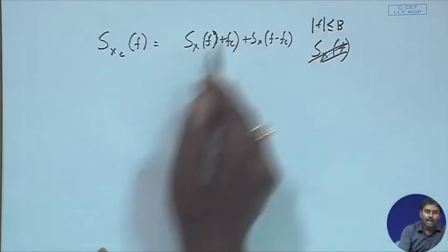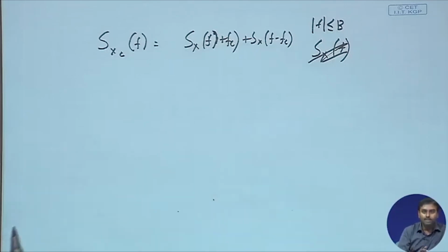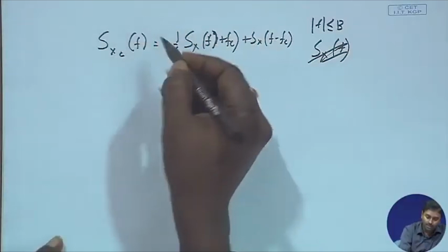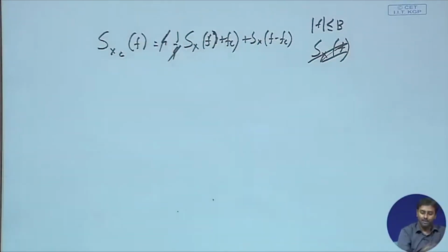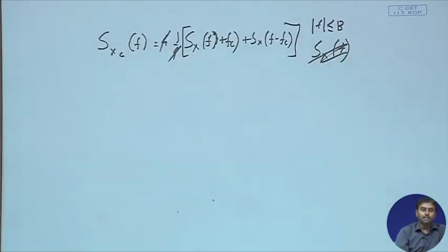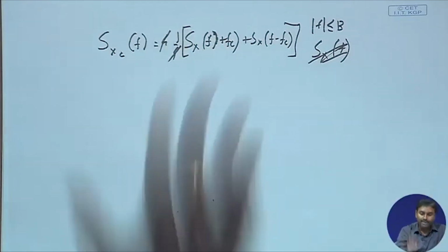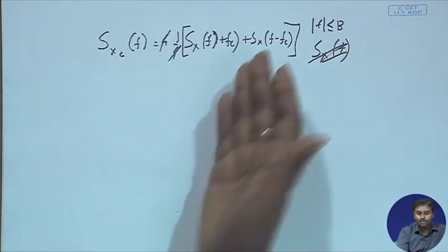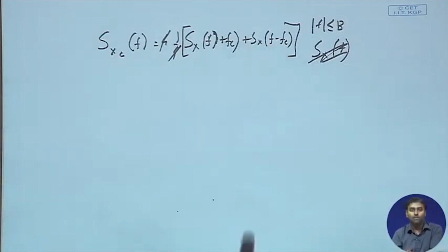It should be this, and then because it is power spectral density, therefore, for cos there will be a half term which will be squared. So, there should be a 1 by 4 and there is a 2 term already that should be squared. So, the 4 gets cancelled. So, this happens to be my power spectral density S xc f. Okay. So, without going into the autocorrelation or cross correlation function, I directly define my power spectral density. As long as x(t) is defined, I can always get the corresponding xc, that is the in phase term, its power spectral density.